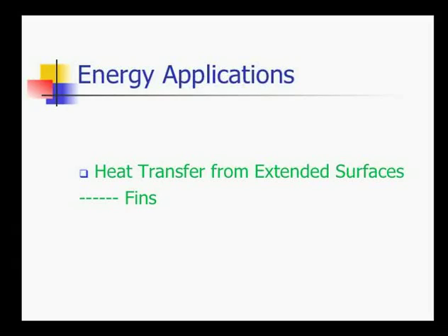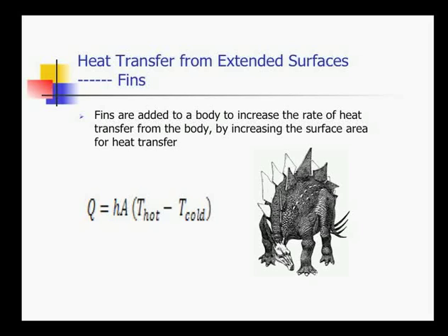Now we'll start with the first energy application, which is the heat transfer from extended surfaces or fins. Fins are usually added to increase the heat transfer from the body. Why is that? Because when we add fins, we increase the surface area from which the heat is being lost or gained, for that matter.